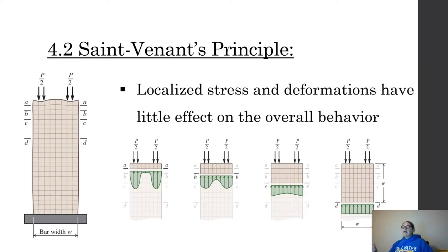So when, again, we look at this, we could look at a different type of loading. The first type of loading was right there kind of in the center. This is kind of offset, symmetric on the sides. It's going to be the same behavior. Once I go one width down, so here's the width, it's back to just the average P over A. Right underneath where I'm applying the loads, it is a much, much greater stress, okay? But it very, very quickly goes back to that average.